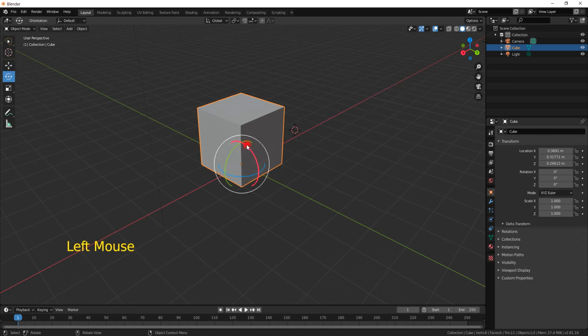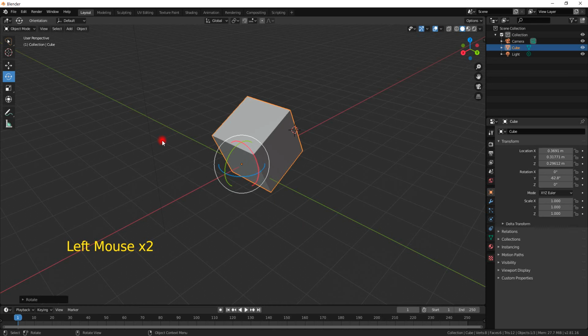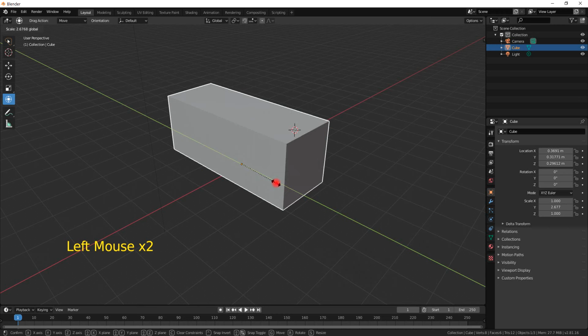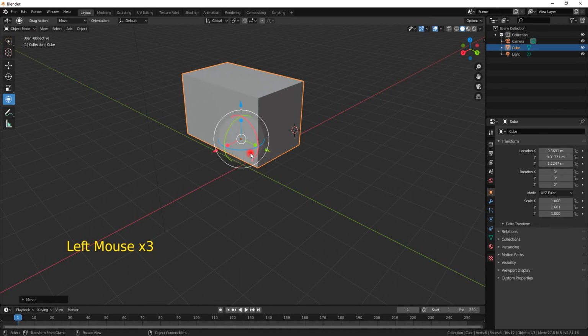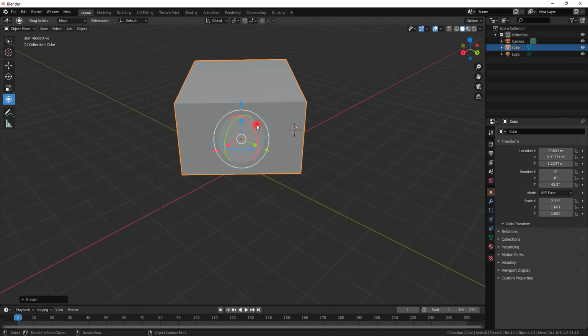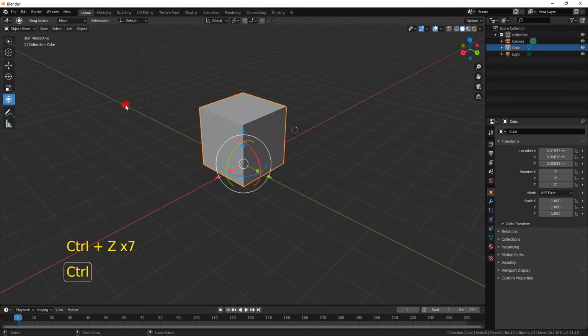The next one is rotation, and the last one is scale. The one in this group of transformations, move, rotate, scale, and transform, enables you to do all of these at one time. But I have to say that this is one of the most confusing views in Blender, so I never use that. It doesn't make any sense to me. Besides, I always try to use the hotkeys, which are G for move, R for rotate, and S for scale. It's so much easier to work with those.